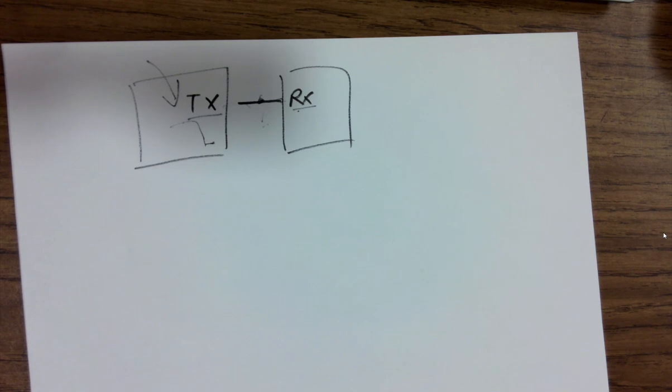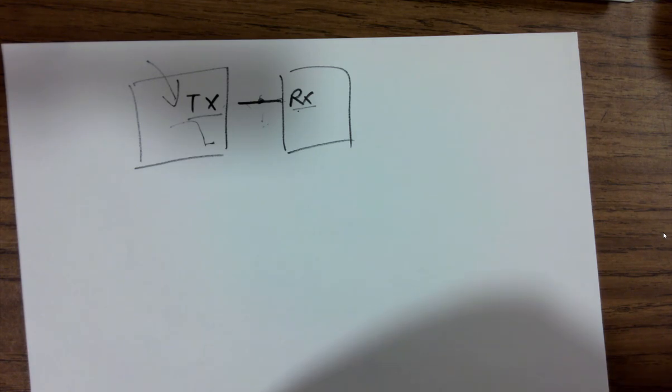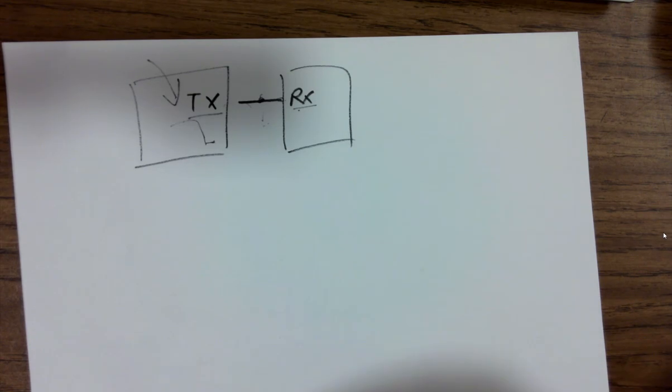You can program it. You can not just detect it, right? If this is getting pulled down, I do something, but you don't really place that start bit or stop bit in your transmission or receiving buffer, because they're not data. It's all the same. It's always 0 and 1, right? Start with 0 and stop with 1, but they're not data. But it's still 10 bits, right? Still 10 bits. So there's 1 byte for the message and 1 start bit and 1 stop bit, right? For question number 17.